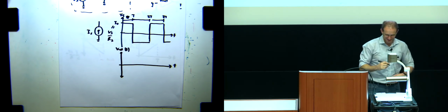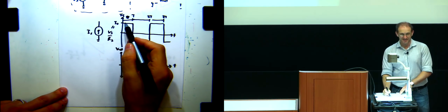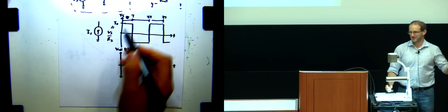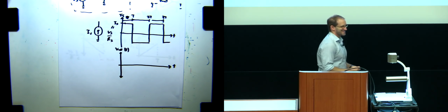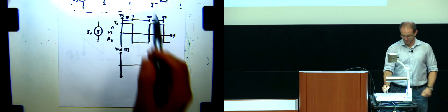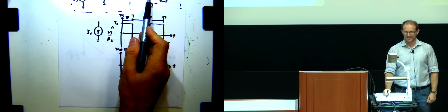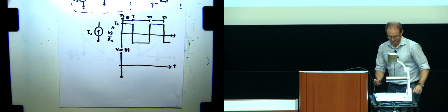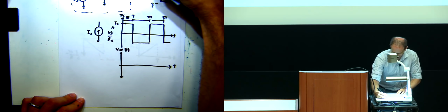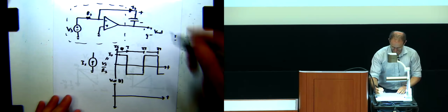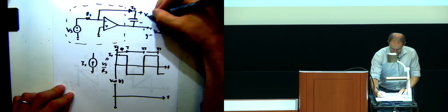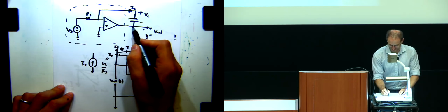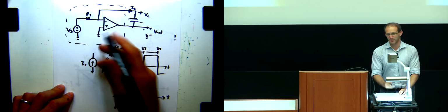Now, to be absolutely clear, when the IS is positive, what will the slope of the V out be? Positive or negative? Careful. Notice where the V out is. Yeah, it's going to be negative, because notice again, if this is where the IS is, and it's positive here, this would be the VC. But the V out, I'm measuring down on the bottom side relative to ground. So it would be flipped over.